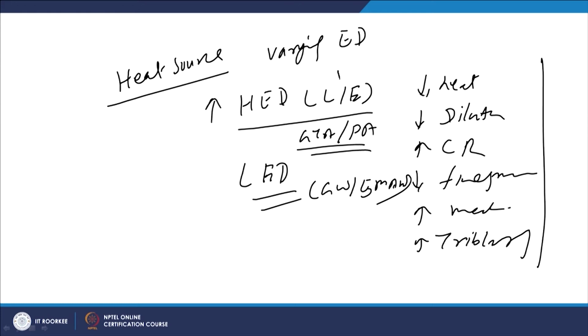So, the best quality is offered by this kind of process with regard to the dilution and the structure, while the poor quality is offered by the gas welding and shielded metal arc welding processes with regard to the structure, dilution, etc. And so, the performance of the weld surfacing which will be achieved.